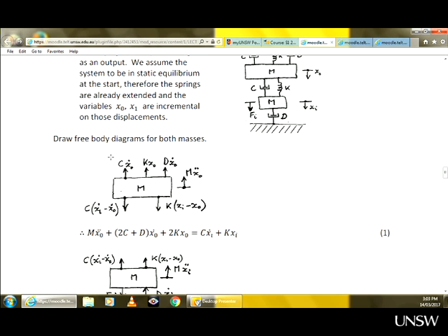What we don't show here is that there is a torque applied. That's why you have all these rotations. But that torque equals the torque across the spring, K1 (theta 1 minus theta 2). That torque is the same as the torque across the damper, which is the same as the torque across this spring. But over here, this torque is not the same as the torque over here, because you have inertia here. Instead, you can write that inertia, J theta O double dot, equals this torque minus this torque.